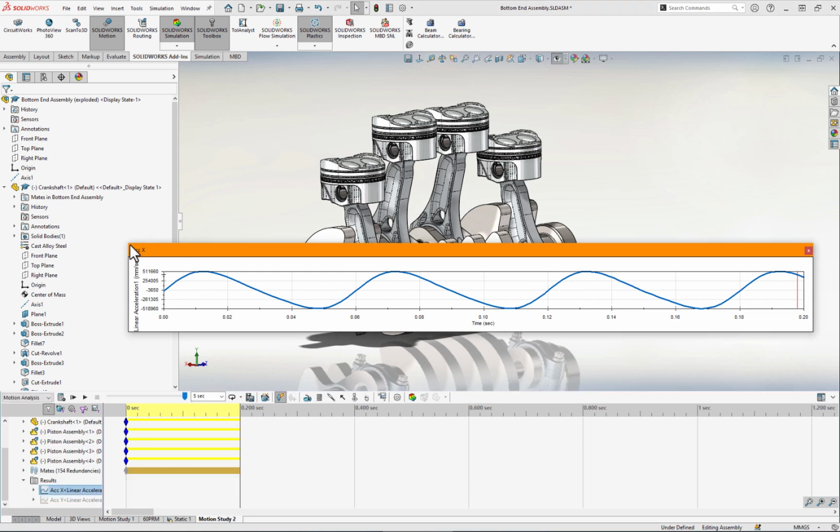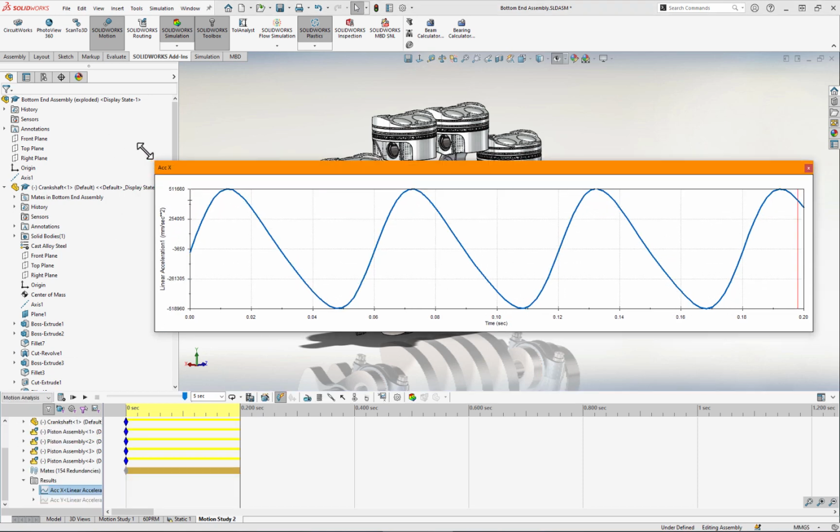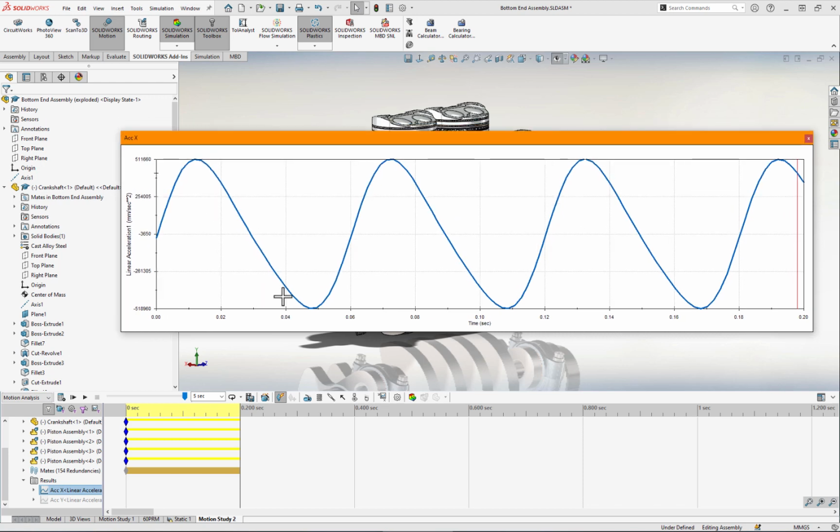Yeah, and that's more like the graph shape that I would be expecting. There's multiple points there, and if you click on the actual plot line itself, you can see the time calculation points. I suspect before we only had a calculation point at every peak and every trough, whereas now we have all these other points that have been calculated and graphed, giving us a much finer picture of what is actually going on during this time period.